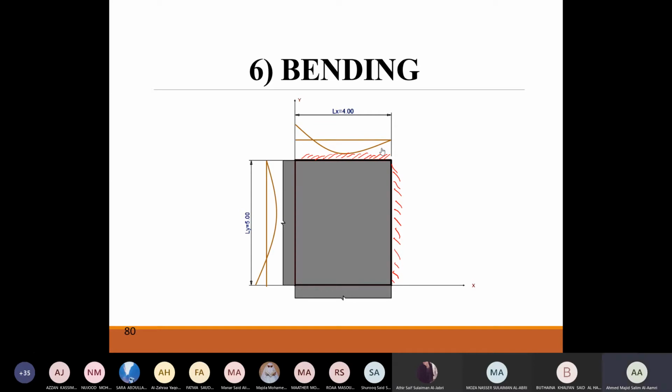In a two-way slab, both of them are main. This is what I was saying. In a one-way slab, it's only one main bar. In a two-way slab, both of them are main. It's main X and main Y. We don't have something called main in two-way. We have dx and we have dy. Both of them are still main. Are we okay with the diagram?